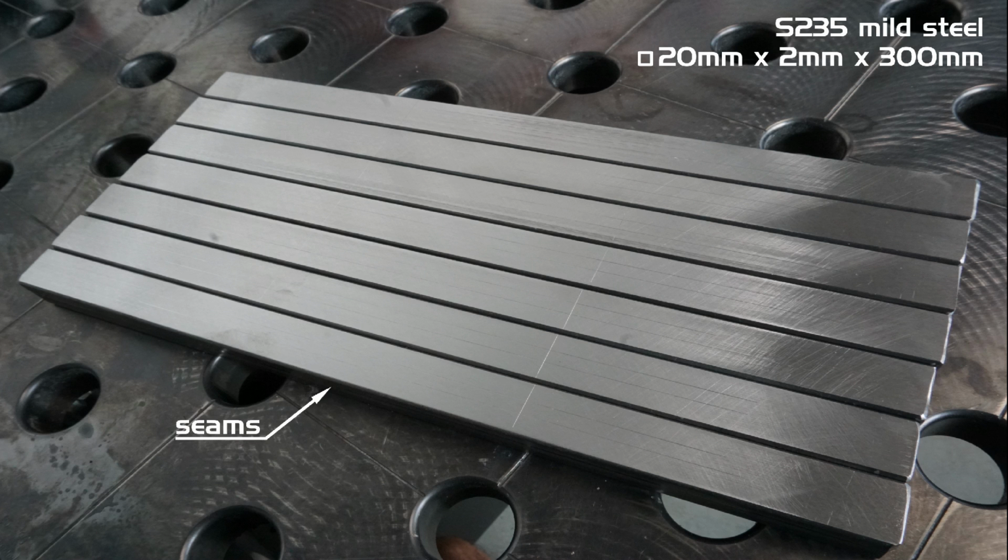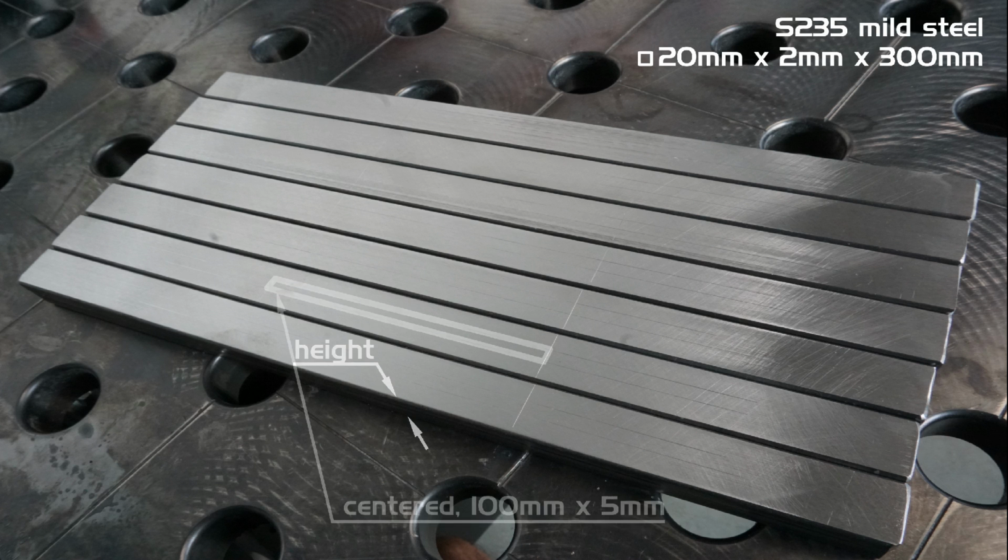The samples are all prepared on the surface grinder so as to have almost perfectly flat and straight top and bottom, as well as to have the same height. This is necessary to allow for a precise measurement of distortion. Weld bead location and target size is marked and equal on all the samples.